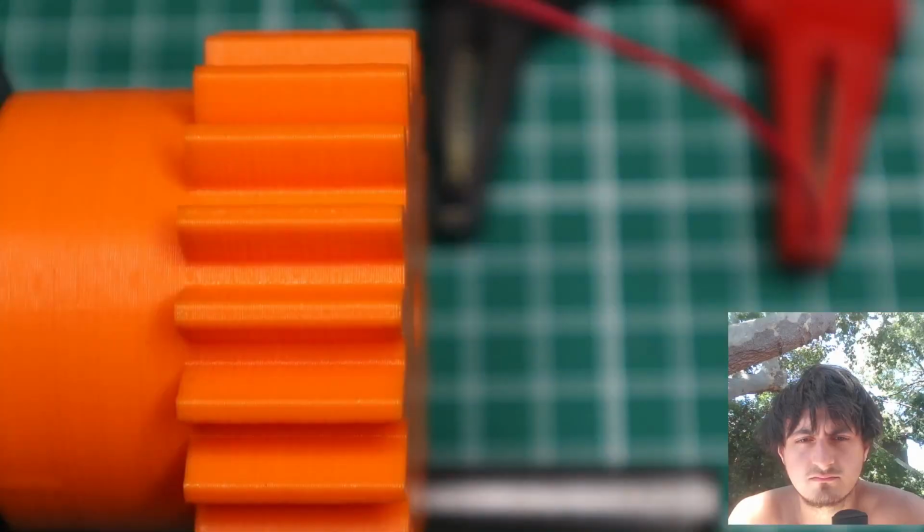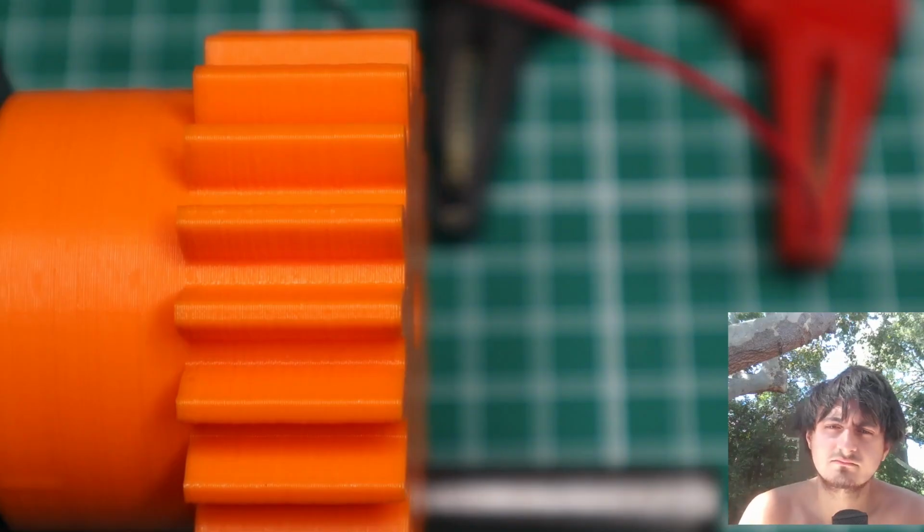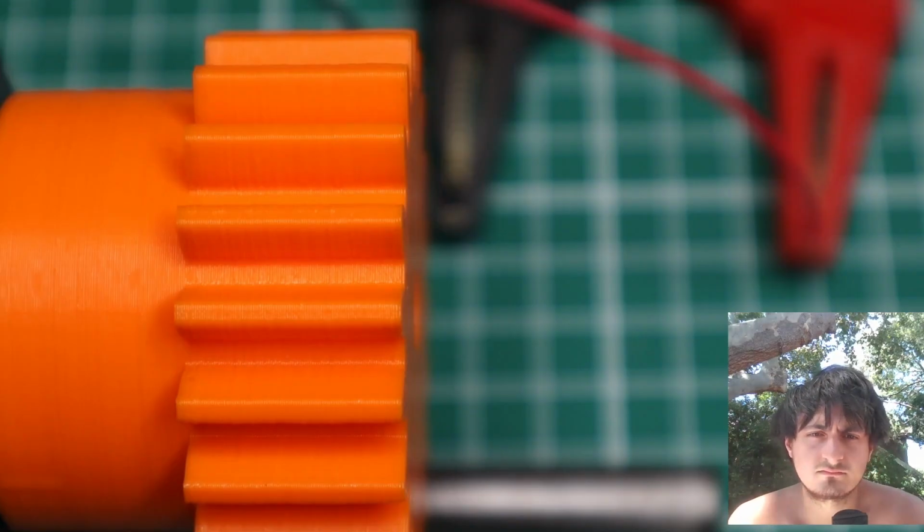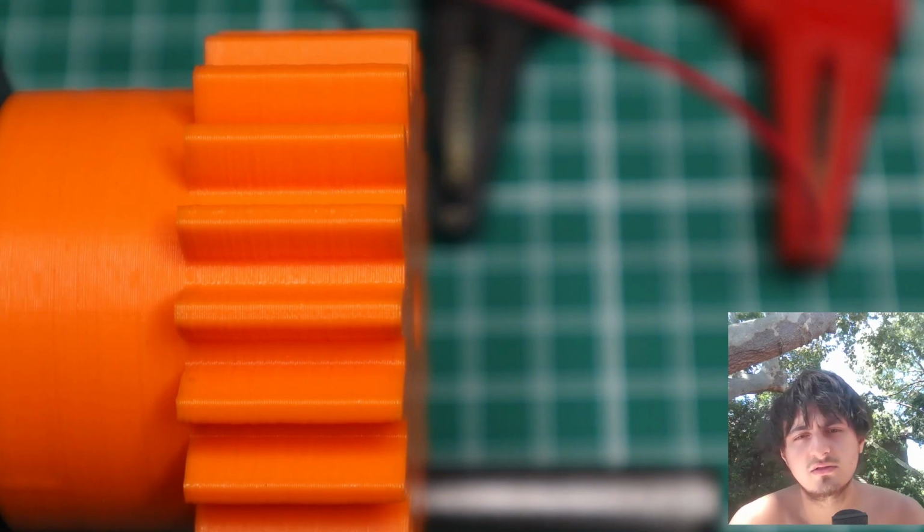This method of attaching the gear to the shaft using only a single set screw does suffer from 2 downsides. First is that there's a lot of force on the nut, and that force is transmitted into the plastic. And because the surface area of the nut is rather small, this creates a very large amount of stress in the material, in the plastic. PLA especially is susceptible to a phenomenon called creep, and this will cause the set screw to come undone over time.